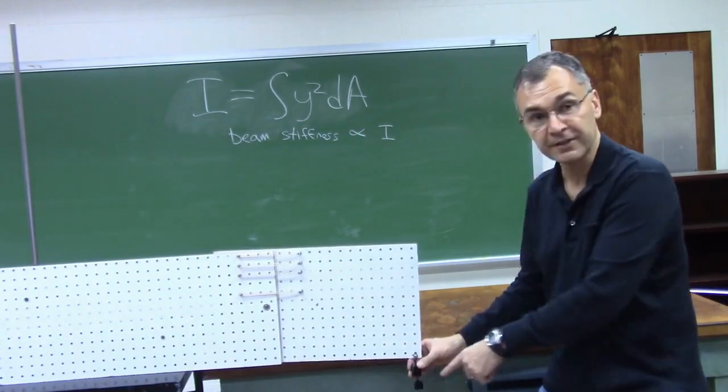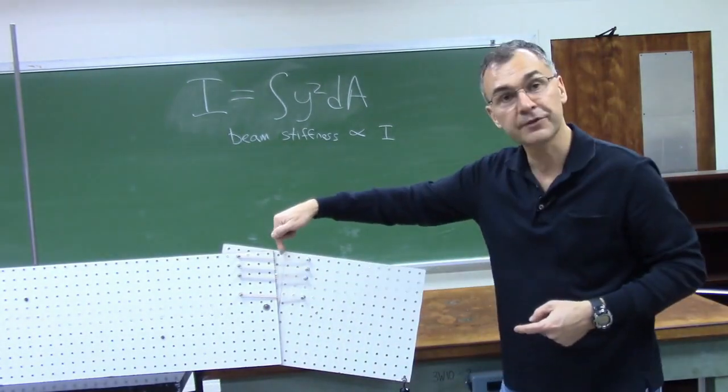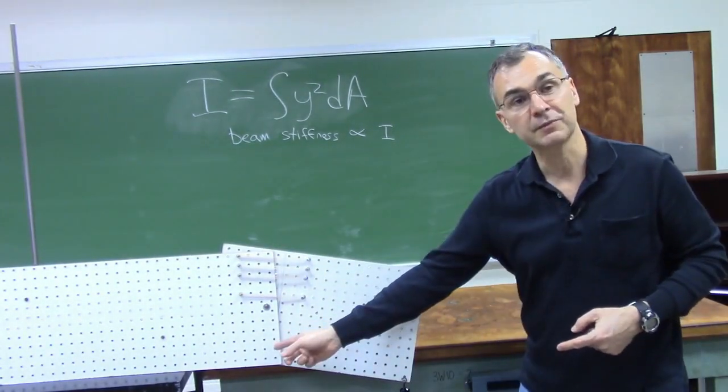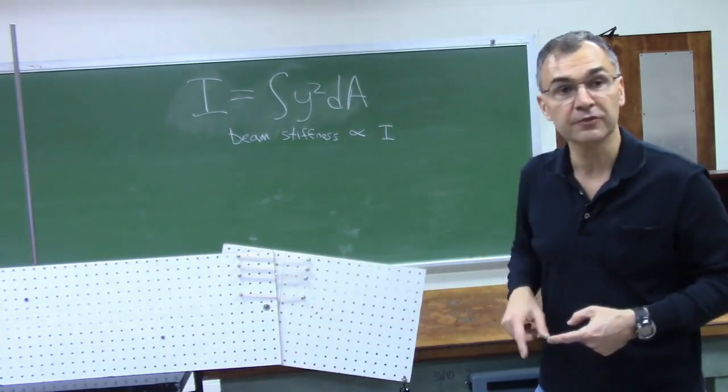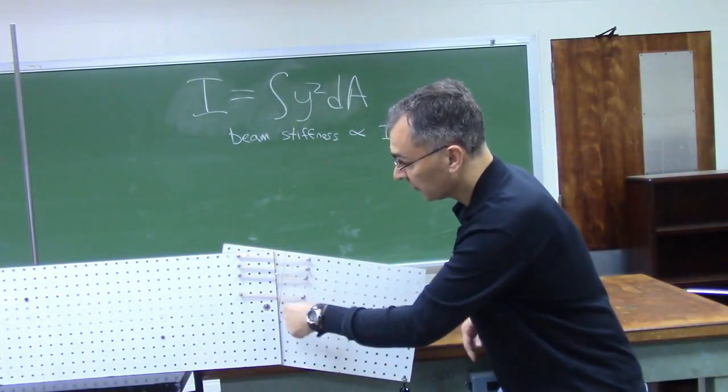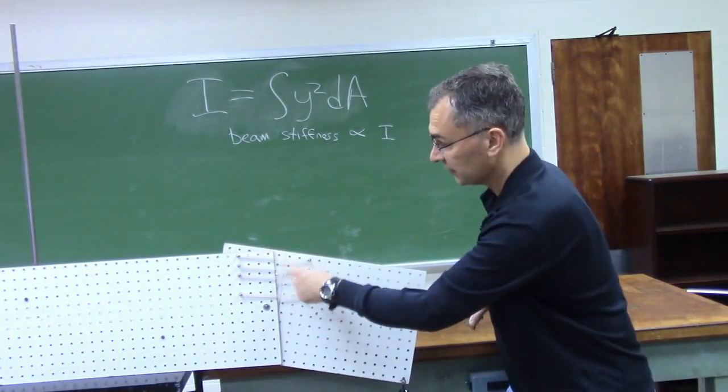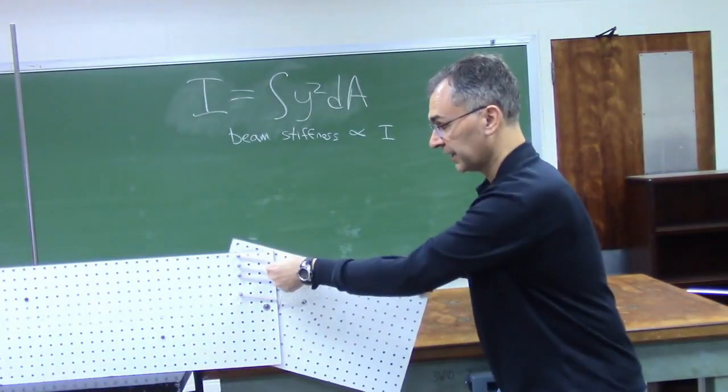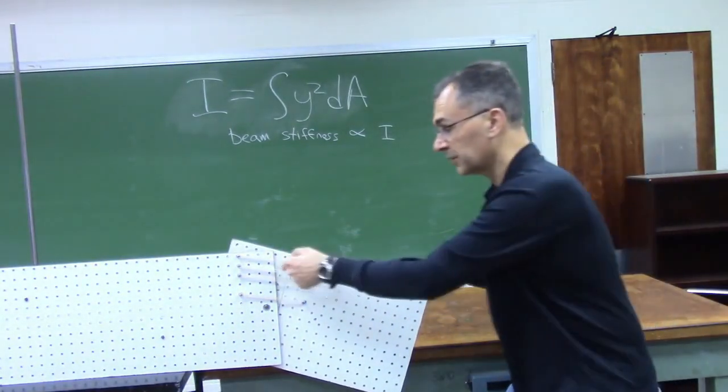So I'll put a little bit of weight here, and you can see now that the top half of this beam is in tension, the bottom half of this beam is in compression. And one thing that stands out right away, if you look at this pencil mark, which a moment ago was vertical, is that the strain, which is how stretched each rubber band is, or how stretched the fibers of the beam are that are being represented by these rubber bands.